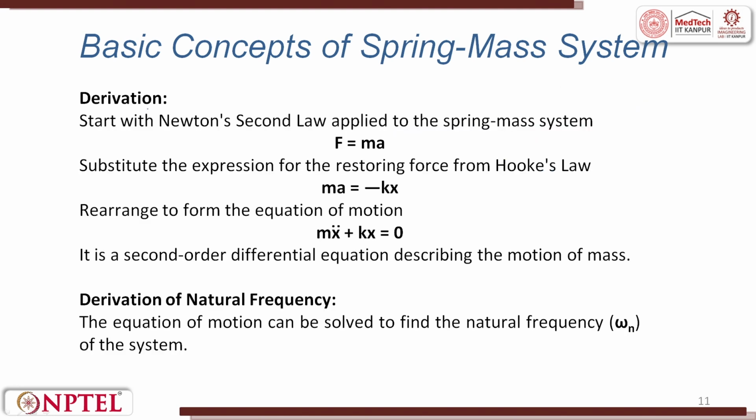So, derivation: start with Newton's second law applied to the spring mass system, F equal to ma. Substitute the expression for the restoring force from Hooke's law, ma equal to minus Kx. Rearrange to form the equation of motion. This is very important. m x double dot plus Kx equal to 0. It is the second order differential equation describing the motion of the mass. So, we have just converted it into a second order differential equation such that we can understand more about the motion of masses.